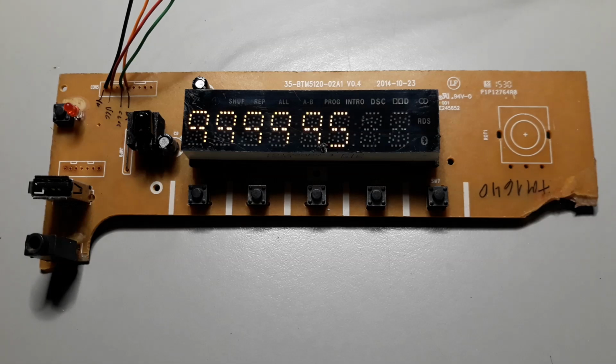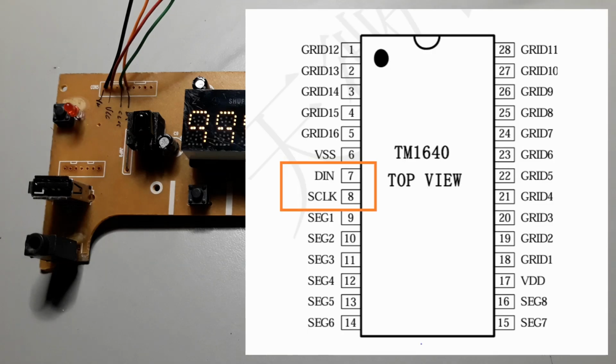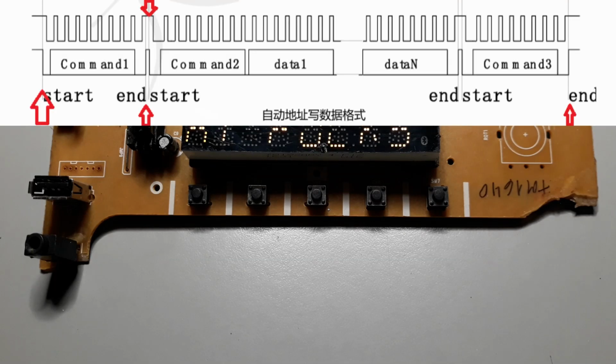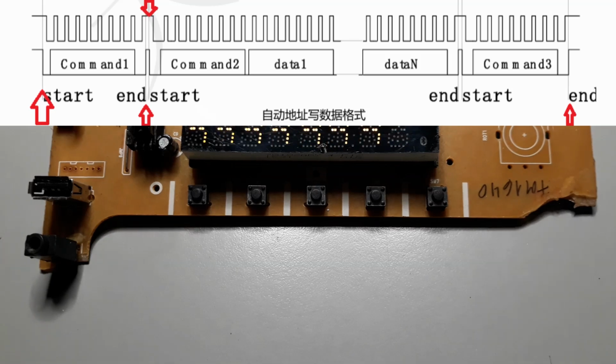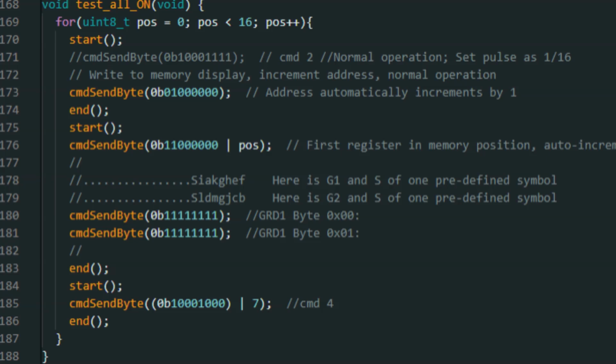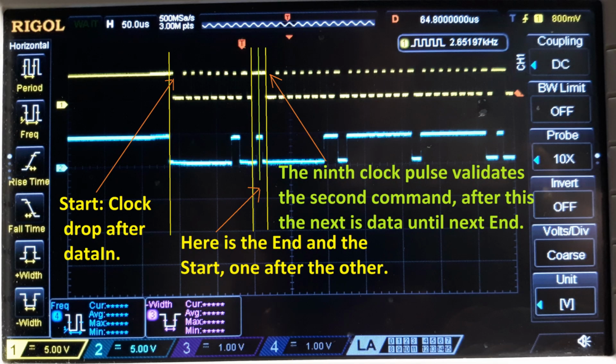One last peculiarity is that it only uses the clock and data signals for communication with the MCU. Therefore, there is no strobe, chip select or chip enable. These details require paying close attention to the use of start and end in the code, because this is the method used to do the handshaking of the communication.